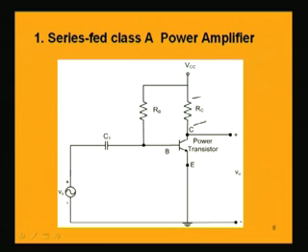Here this RC is causing a power wastage, and we have to devise some means to reduce that power loss which is occurring in the RC. So, in order to increase the efficiency of the class A amplifier, a transformer coupled amplifier is used because of the much wastage of power occurring in this RC which is connected in the collector.